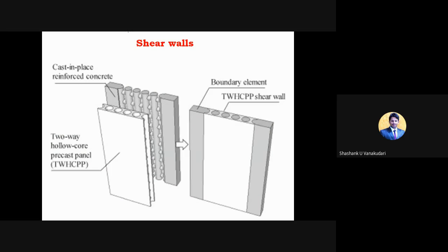So, a shear wall is a structural member that is used to resist lateral force. Whatever force comes through the horizontal mode, those forces are going to be resisted by these shear walls, parallel to the plane of the wall. For slender walls where the bending deformation is more, the shear walls resist the loads through cantilever action within these members.